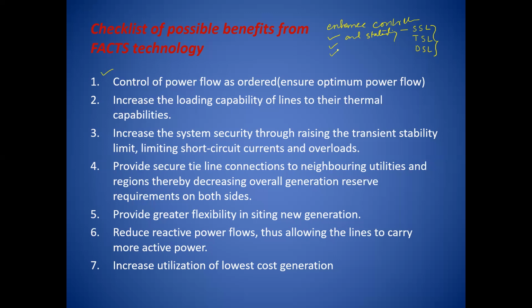So if you are moving toward more than 765 kV, definitely we have to think about the dielectric strength. Whereas the thermal capability depends upon the amount of current flowing through the conductor and the climatic or geographical condition where the transmission line has been erected.